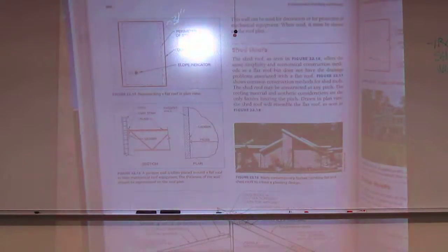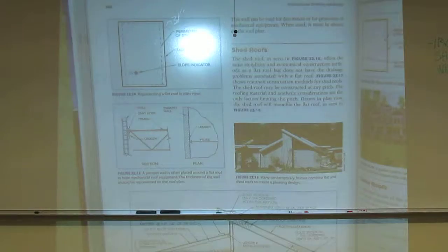When you guys say they're taking gravel off, what have you seen out there? What else have you seen on a flat roof? I've actually done flat roof training with GAF. So I have done TPO, PVC, foam, and hot tar, but nobody does hot tar because it's expensive and it's dangerous. And people don't do torch downs anymore either for the same reason, because you can't carry insurance on a commercial company and afford it to have somebody up there with a torch burning tar.